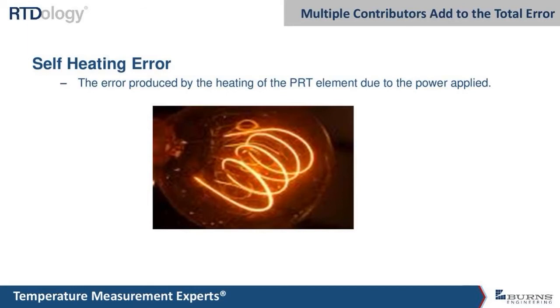Self-heating. Since the probe is actually just a resistor made out of platinum wire, as soon as you run an electrical current through it to measure its resistance, it's going to heat up just a little bit. Same thing as what you'll see in an electric space heater. You throw some power to it and those resistance coils start to get all red and they heat up. Well, at a much lesser magnitude, the sensors do heat up slightly. This, again, can be a pretty small error.